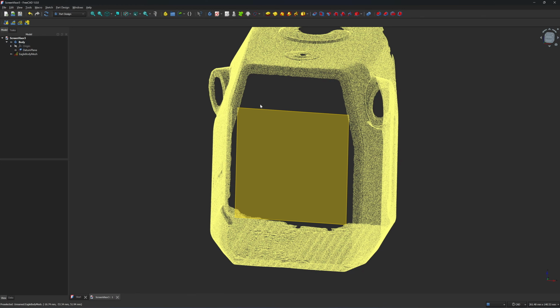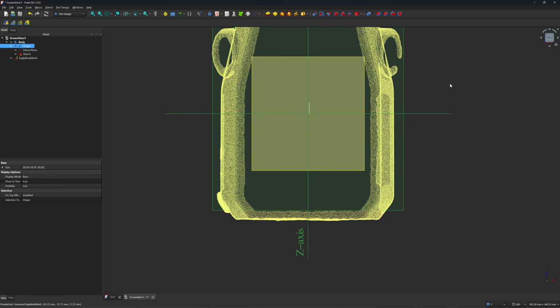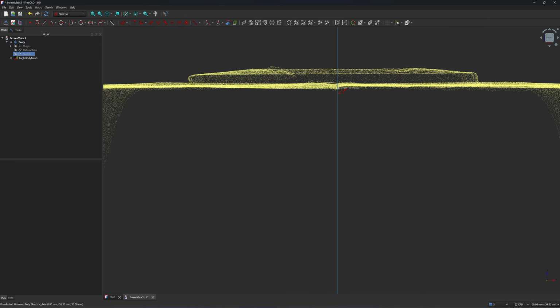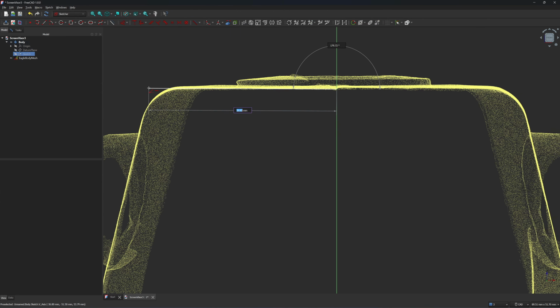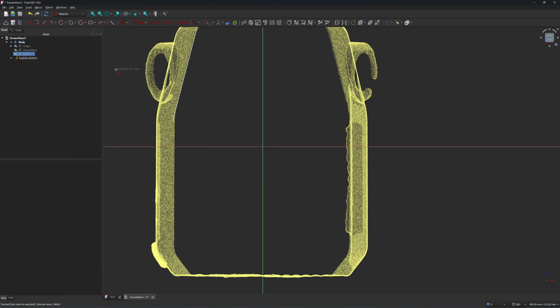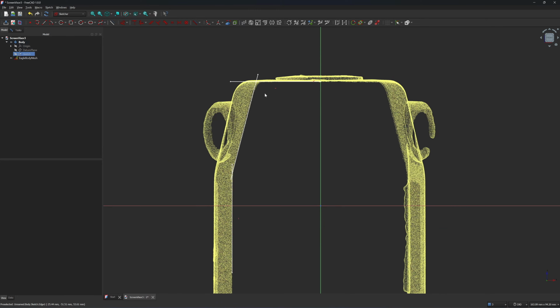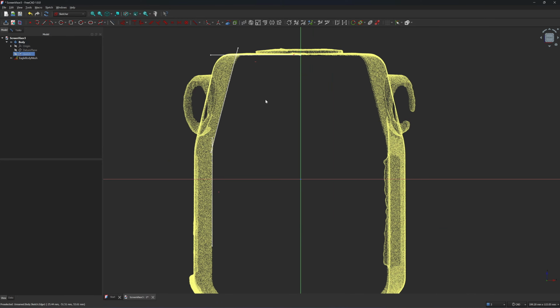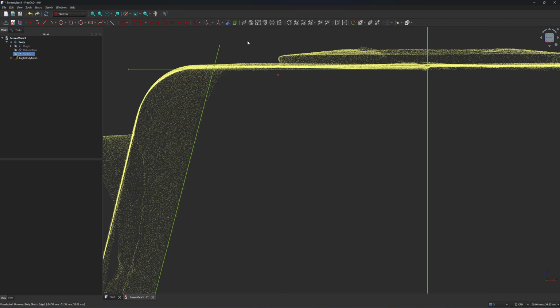Okay, next I'm going to click on the plane, click on create a new sketch at the origin point. Click on this line, horizontal line, second line, horizontal line. Okay, here's a third line. Okay, so everything looks alright. So I will lock all the lines in place. Now it's locked. It's turned into green color. It means that it's locked.